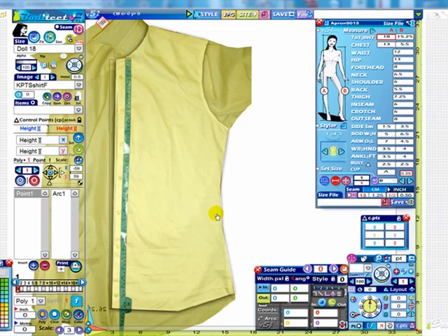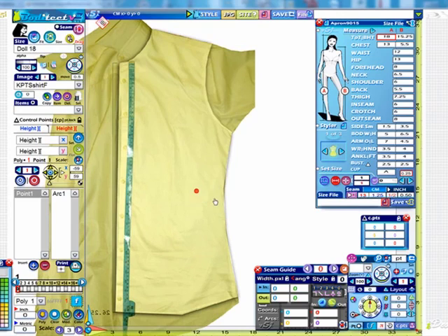So that will introduce you to using images, and how to set them up in your digitizing area. The screen replaces the function of those traditional large digitizing tablets, which are used in CAD design and engineering offices. As you can see, we can just use our screen and set that up, lock our pattern piece, and then go ahead and draft out the points for this particular pattern piece.